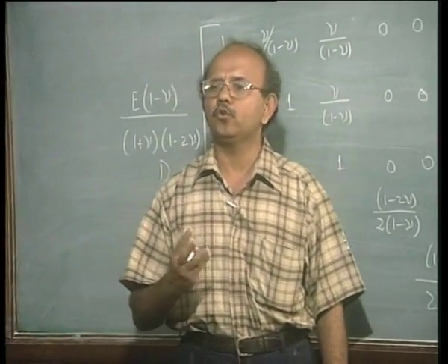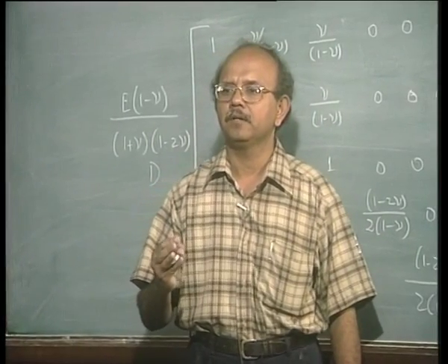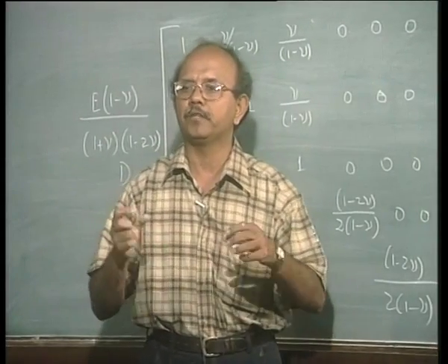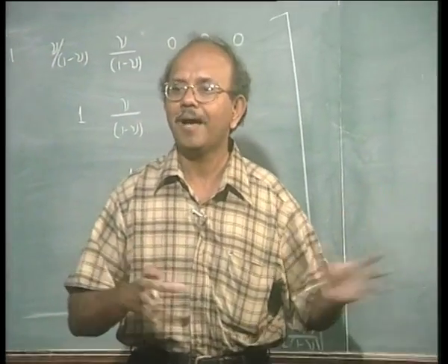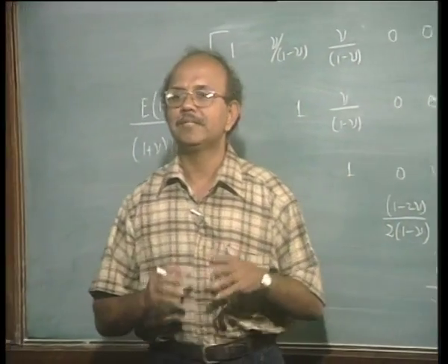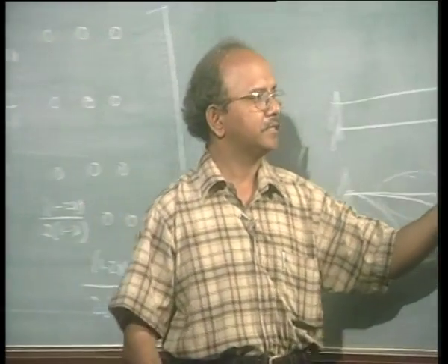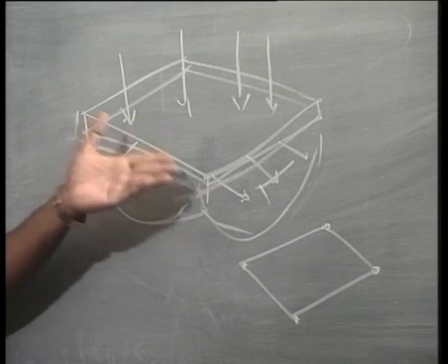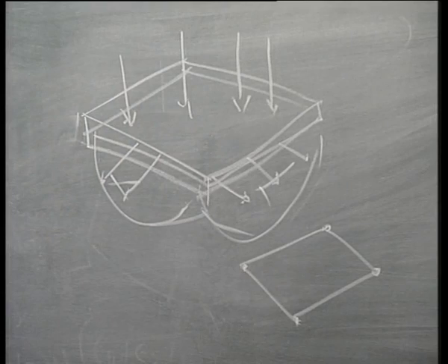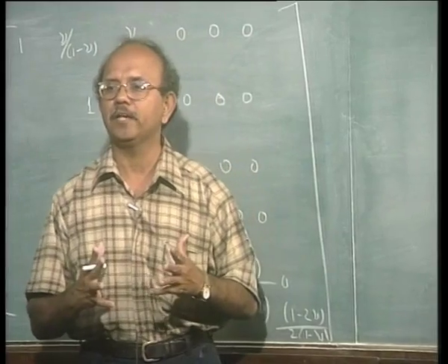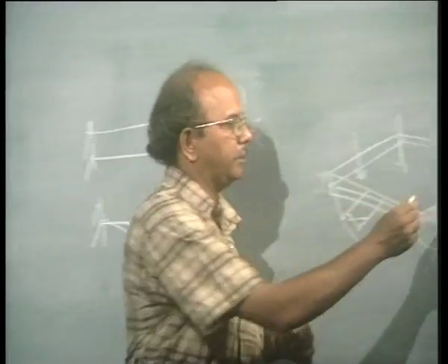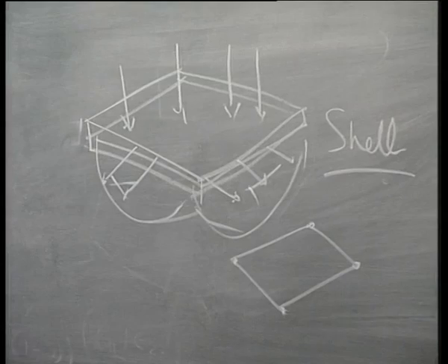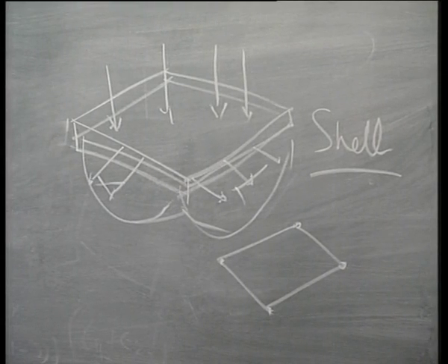But nowadays people don't use a plate element separately. For example, a bar element can be combined with a beam. Now look at that beam which we did. There is no need for a separate bar element because that beam had the effect of a bar as well. Similarly, though technically speaking this is a plate, the in-plane behavior, or the in-plane forces and corresponding stresses, can also be taken into account together with this bending behavior, and the result is what is called a shell.